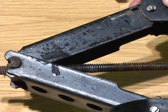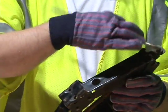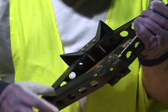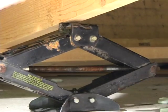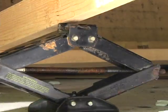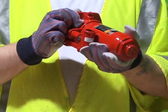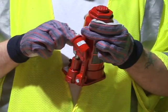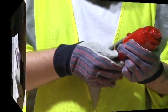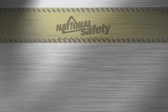Lubricate jacks regularly and inspect at least once every 6 months. Inspect jacks that leave the worksite upon return and before each use. If a jack has been submitted to an abnormal load or shock, it should be inspected before use and immediately thereafter. Hydraulic jacks exposed to freezing temperatures must be filled with an adequate amount of proper antifreeze to keep from freezing. Check with the manufacturer for the proper type of antifreeze.